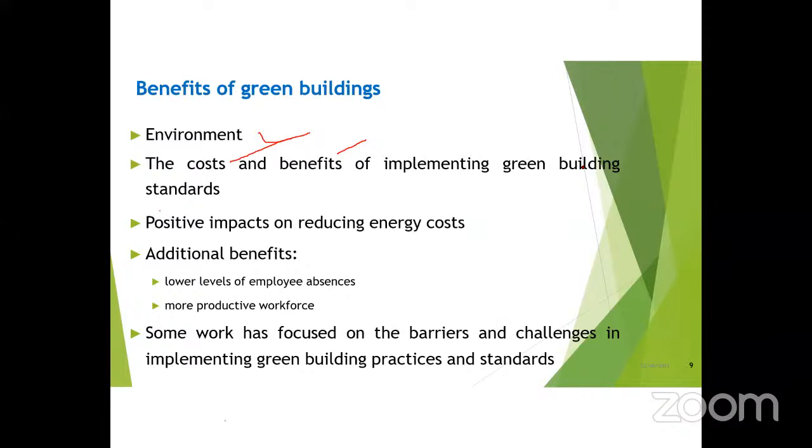Reuse of water is there. You can recycle your gray water by different systems, you know, the wastewater management system. Most of the used systems for grey water are rapid root zone treatment or constructed wetland. That means the roots of some species are natural cleaners for the wastewater, and the water quality is good. So that water is also recycled and reused for gardening purposes. Then we are using the dual water flush system. Next, the aerators in the shower are also installed in the green buildings. So with such small alterations, green building consumes 40 to 80% less water than the conventional building.